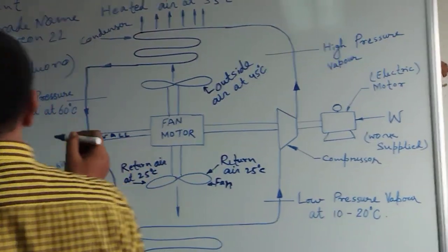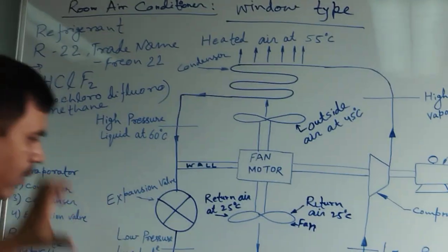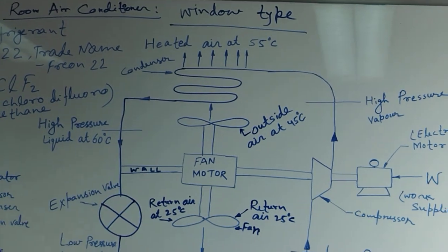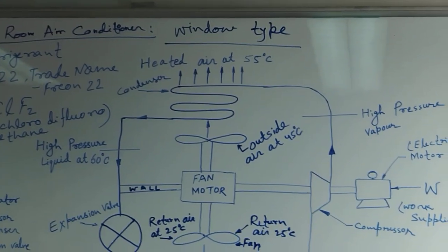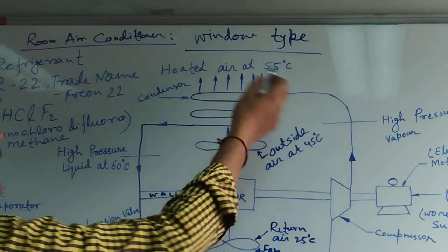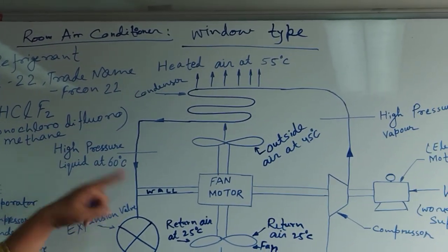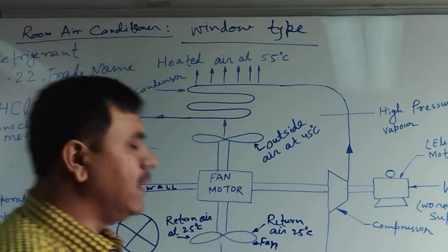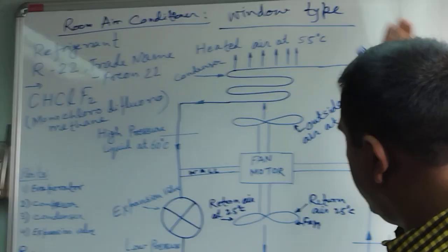Monochloro-difluoromethane. Okay, this is the refrigerant. We use this refrigerant to work at a temperature of 5 to 10 degrees Celsius. It will be high after passing through the compressor, it goes to about 60 degrees Celsius.